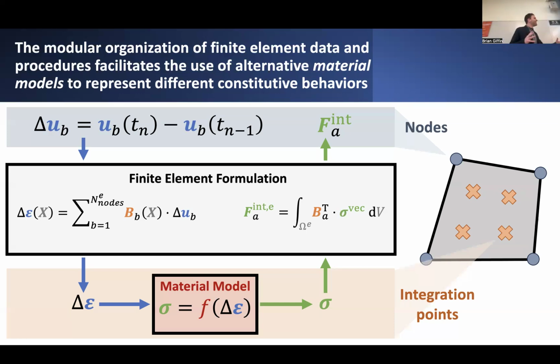But at the end of the day, our finite element formulation remains the same. If we're interested in generalizing this relationship to accommodate nonlinear material behavior, the only thing we have to change in this diagram is the material model. Everything else we can leave as exactly what we've discussed up to this point in the class. So our finite element formulations that involve computing these strain displacement operators, using numerical integration to integrate things over the elements to compute those nodal forces, all that is consistent with what we've discussed. It's really just this part that we have to touch if we want to include nonlinear material behavior.